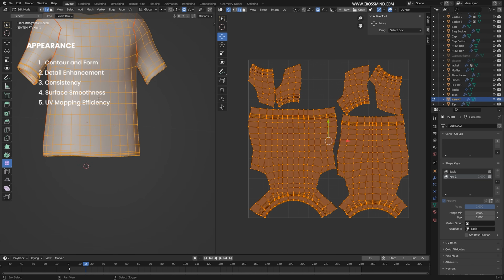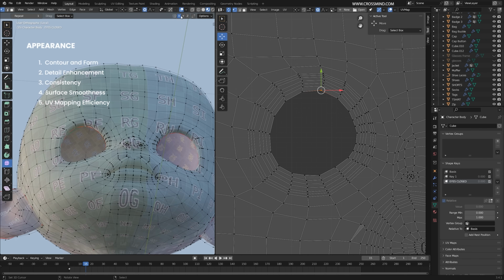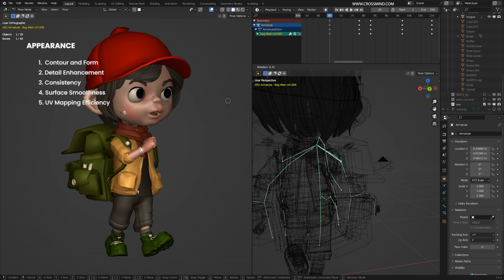Selecting loops, cutting down the mesh, modifying the geometry, laying it flat for UV is a much easier task, and often if the topology is cleaner, there's less chance for distortion and visible stretching in textures.